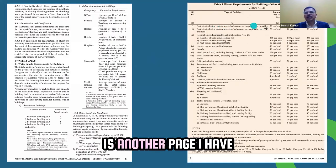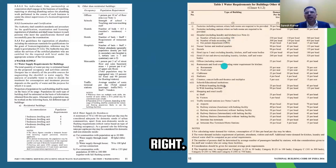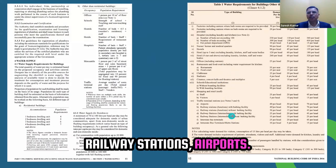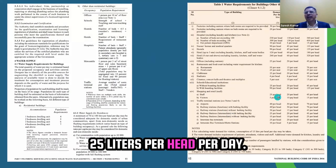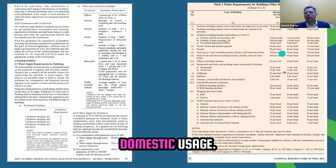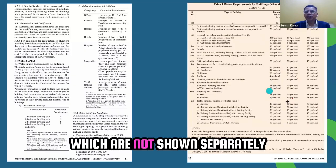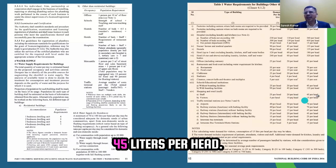On the right side, this is another page I have extracted and put here. Factories with canteen, factories without canteen, right? Nursing homes, cinema halls, shopping malls, railway stations, airports. You are seeing shopping malls here, 25 liters per head per day. And where is this going to be used? 25 liters is for domestic usage. That means there could be some restaurants, etc., which are not shown separately in a shopping mall. So in a shopping mall, it is advised to take 45 liters per head.